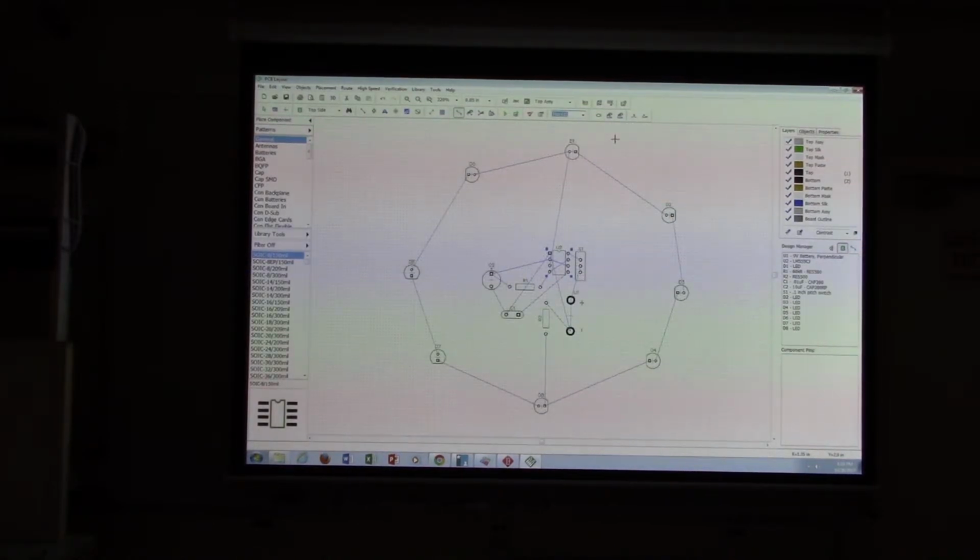So you can switch between those. That brings me to another point, which is that for our boards, we want the LEDs to be facing you, and we want most of the other components to be facing away. Your design is primarily going to be flashing LEDs. So when somebody looks at this, you want them to see the LEDs.